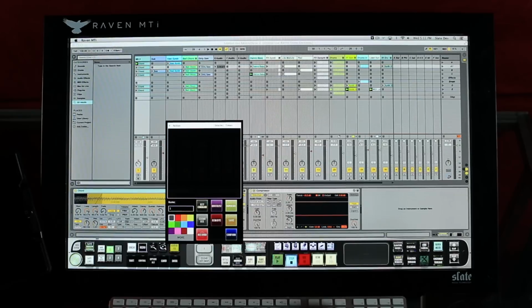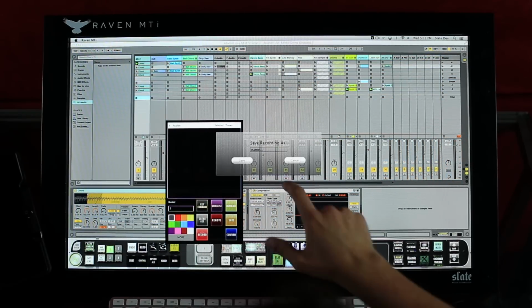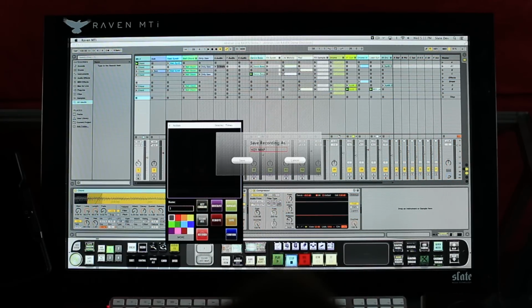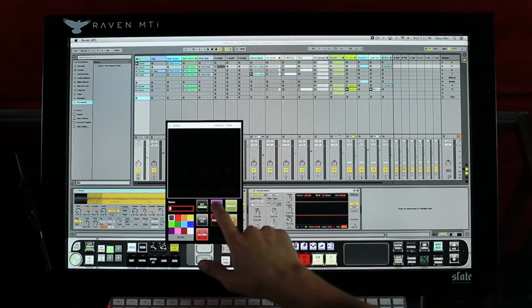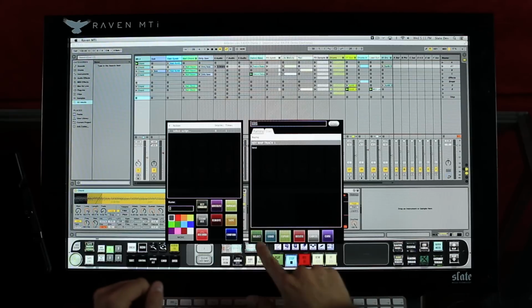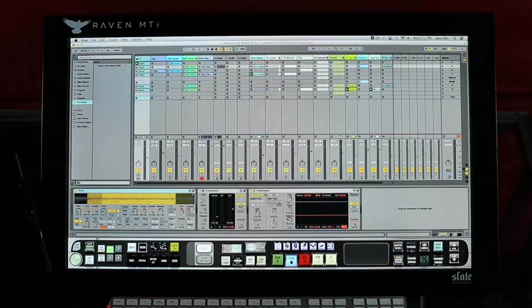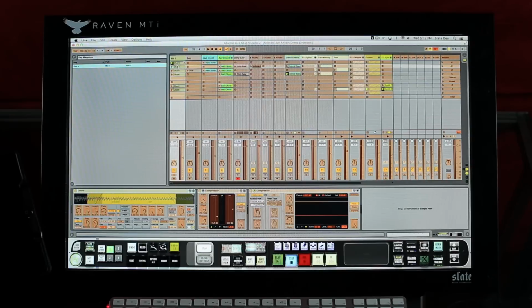Now we'll hit the record button and watch the batch command system record your mouse clicks and key commands in the sequence you perform them. Once completed, hit the record button again and name your new batch command. This will save to your User Recordings tab for later use as well. Now I'll just add my new recording into the batch command line, give the button a name and color, and hit Confirm. Now watch my new custom recorded batch command perform a key command and mouse click.